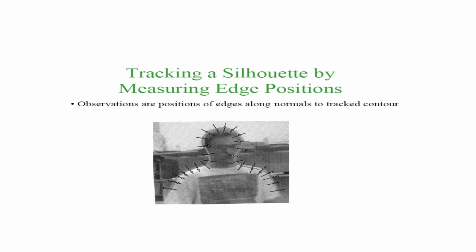So, it could be your target-oriented measurements and some false measurements together; your sensor will give you the data. Now, you have to find it out. You have to write your algorithm, which tells which measurement belongs to my current actual target and which is a false alarm. It could also so happen that all measurements at a given scan are false alarms, and there is no target. You have to find that out. That is the purpose of target tracking. Okay. I will go into details in the subsequent sections.